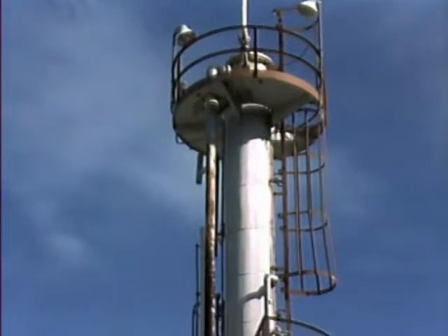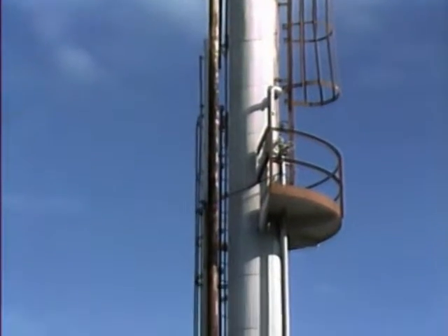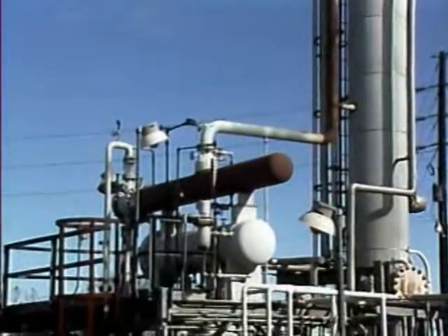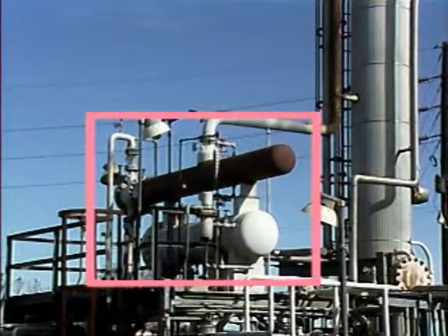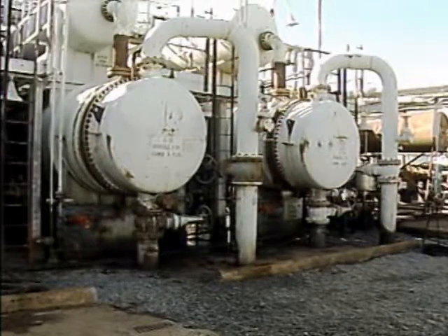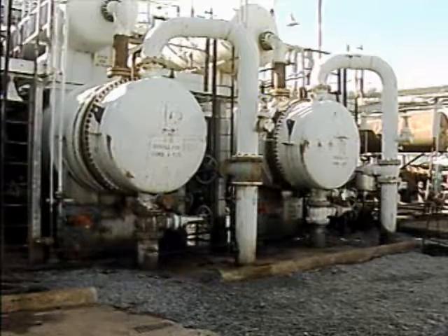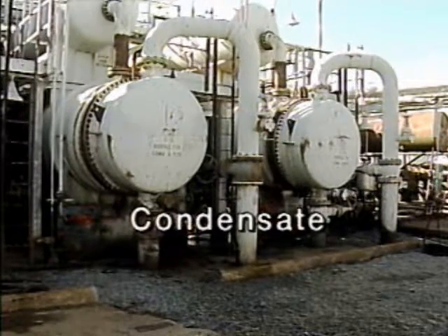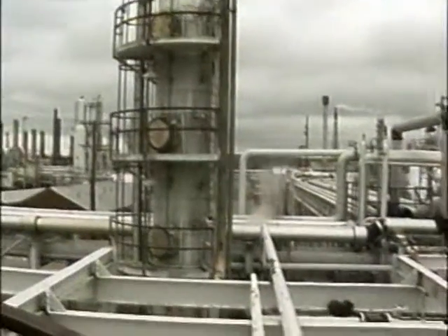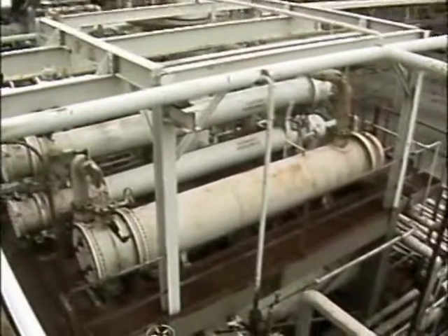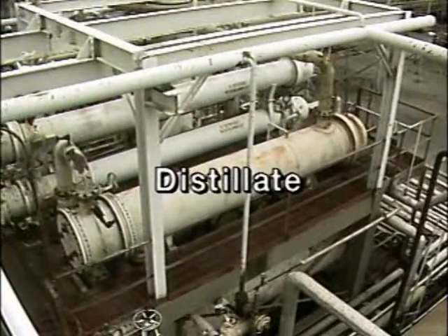Condensers can also be used to cool and condense product vapors. For example, the vapor produced in this distillation column flows into a condenser and is converted to a liquid. Depending on the process involved, the liquid formed in a condenser may be referred to by different names. The water that's formed when steam is condensed is called condensate. On the other hand, the liquid that's formed when product or byproduct vapors are condensed is often called distillate.